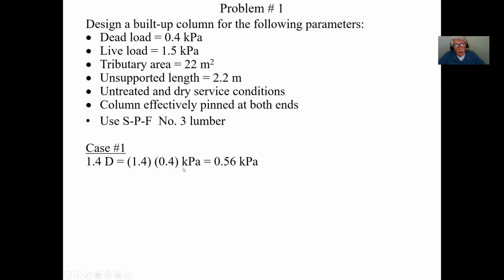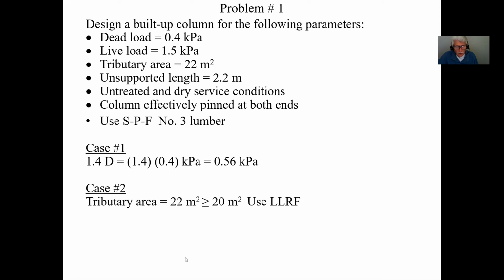small. Now, for case number 2, because I've exceeded 20 square meters, if you want, you can take advantage of the live load reduction factor. That's up to you. You've got no obligation to do that, but as soon as you exceed 20 square meters, you can use the live load reduction factor. And it kind of makes sense, guys. You have to remember, here you're talking about 400 square feet. That's the limit, you understand? 20 square meters is about 400 square feet.